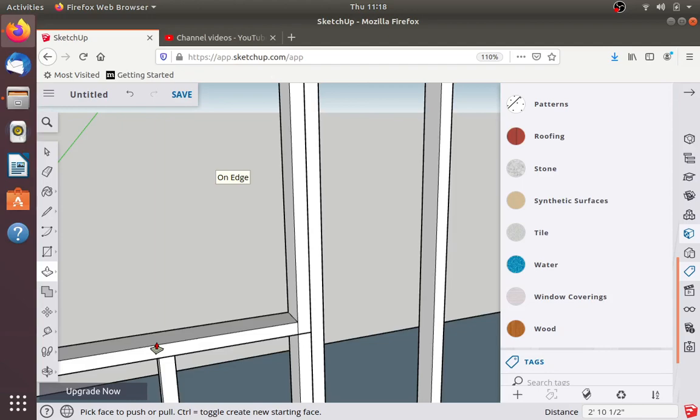Okay. So that's the correct way to make a window. And a door should be the same, although your door is going to be much skinnier. If it was a door, I'd probably go between here and here. So that's the proper way to make your window or a door. You want to make sure you've got these support boards here, a support board here, and that upper board is going to measure 7.5 tall.